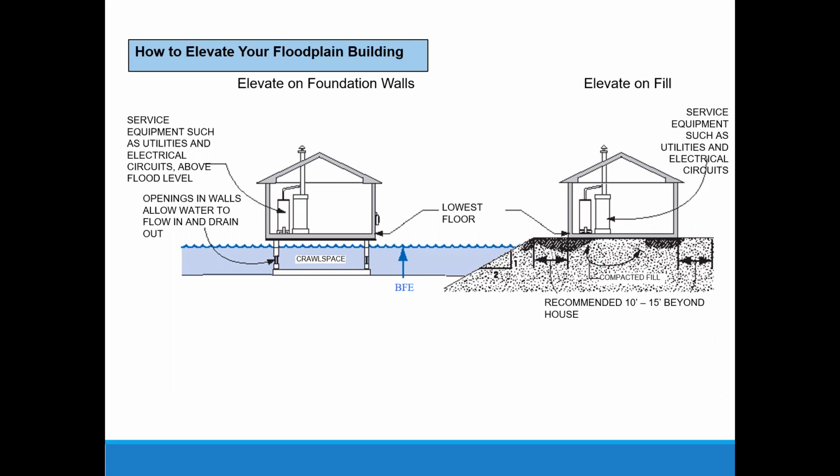One of them is on compacted fill. We have fill dirt that's brought in. It's compacted in a way that has to be compliant. I have another slide on the standards for that, but it's about 10 to 15 feet beyond the house for that fill pad to go in. And then of course, taking that out of the floodplain would be the LOMR-F from FEMA.